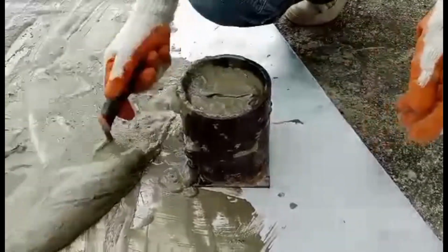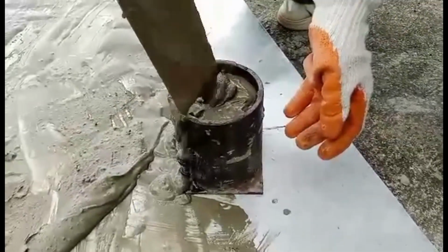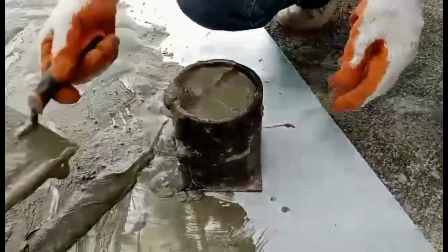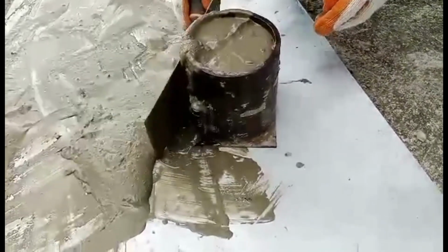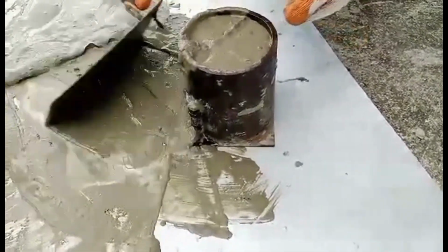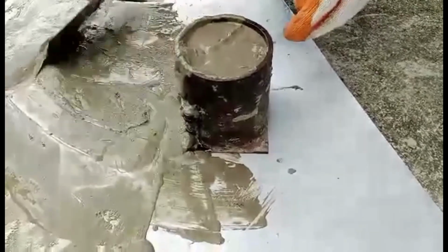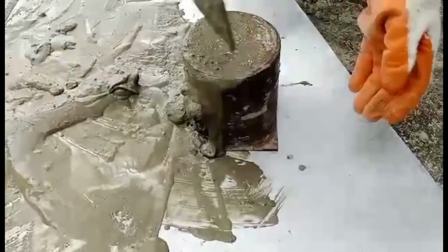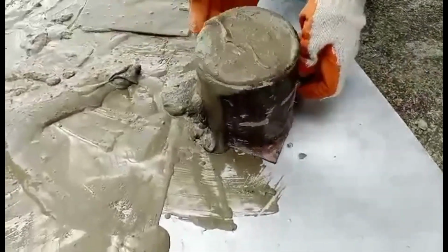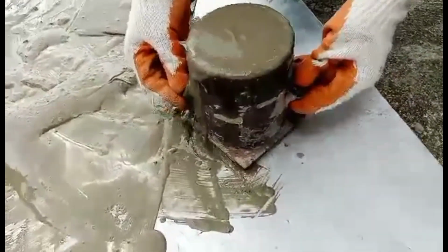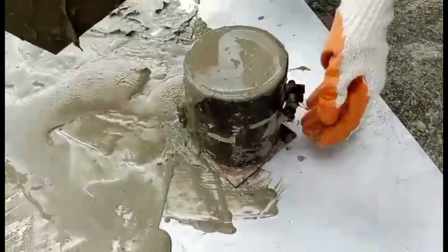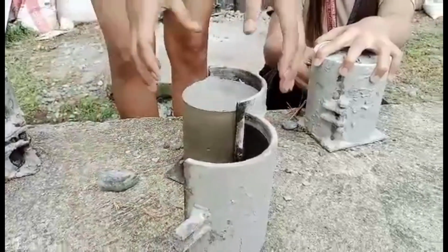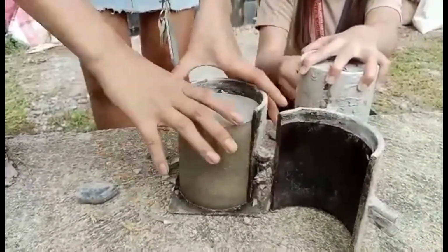After mixing, we conducted the slump test for each sample. The mixture was then placed into cylindrical molds. The mortar and paste were stored for 24 hours in a suitable location, and after the said duration, the specimens were then detached from the molds and curing for the mortars and cement paste took place.